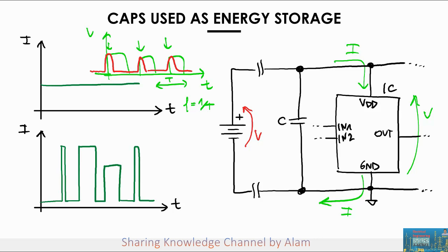So that is why most likely the current for CPUs and for integrated circuits looks much more like this. Now, the average current that is required might very well be similar to the example above, the constant value of the current. But the actual waveform is completely different. It has a lot of spikes, bursts, and ups and downs. And that is why, as we'll see soon, you need to have bypass capacitors in order to guarantee a constant voltage at your device.